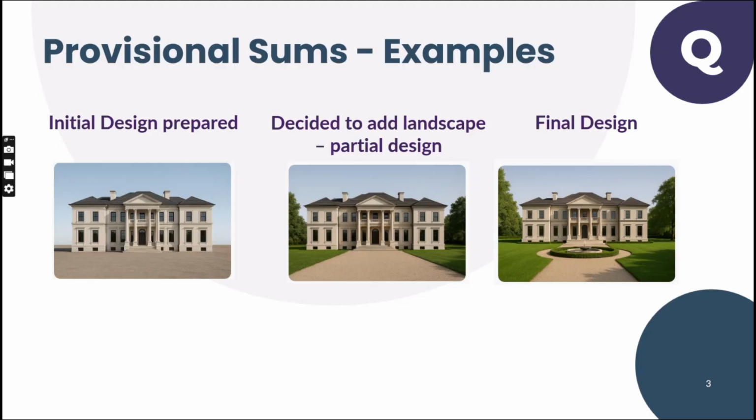So in most cases there will be a separate BOQ, or bill of quantity, for the provisional sum items. Let me tell you this way: when you start the contract, as a first condition, you have to submit the performance security. Performance security will be submitted on the accepted contract amount, excluding the PS items.